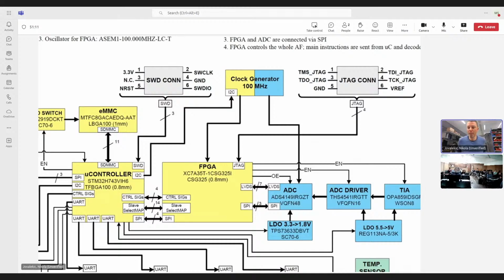Yeah, maybe suggest a third approach. So maybe you can put the clock generator a bit further from this part, and let's say use a longer interconnect. But then I would apply certain techniques, like for example via stitching around the track, to protect the rest of the PCB from this, let's say, highly noisy interconnect. You understand what I want to say? So maybe something like this.